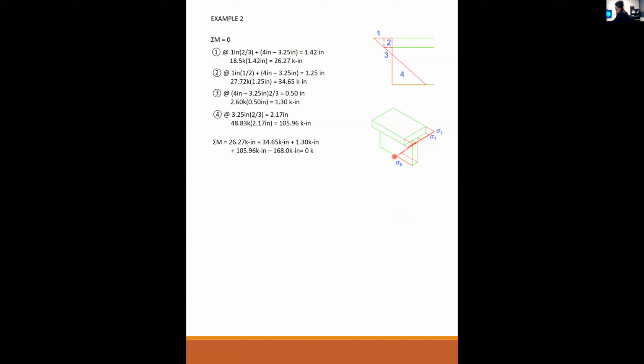It's constant across the bottom of the flange. It's constant everywhere. So as long as the moment is only in one direction, about x, and there are no moments about the y-axis, then those values are going to be constant.